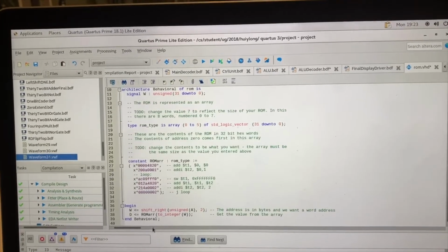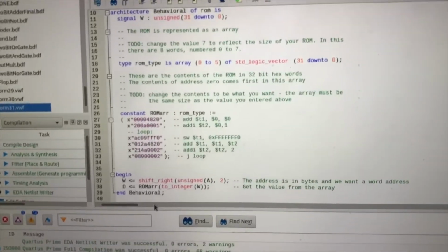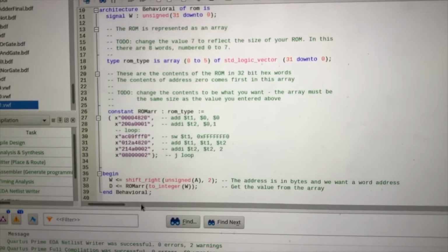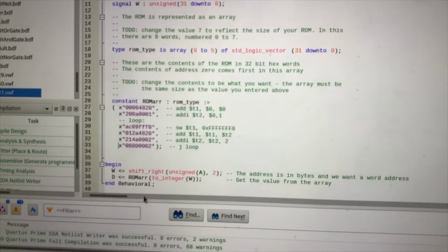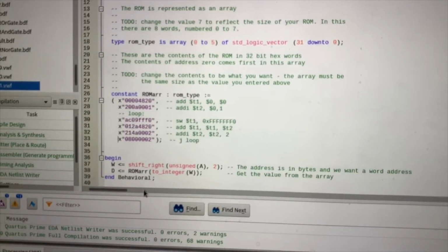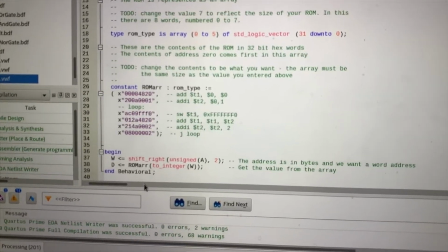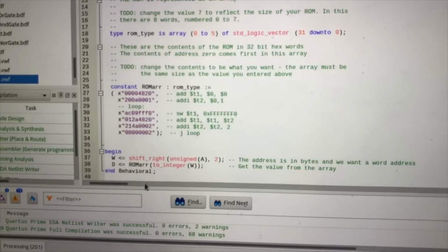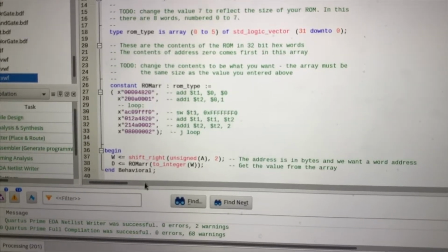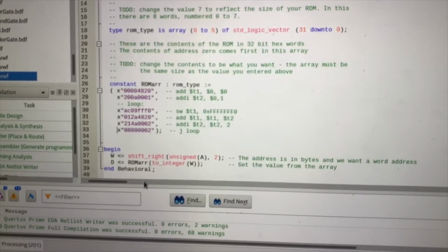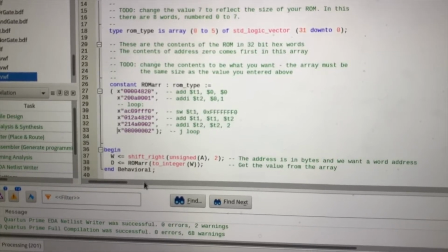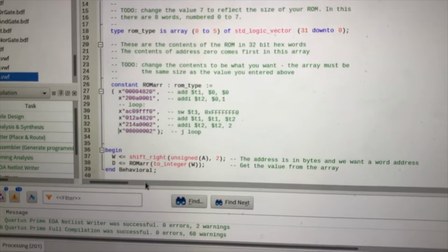This is our square numbers program that we wrote. In the first line here, we add 0 to 0 and store it as st1. In the second line, we have st2 where we used addi to add 1 to 0 and store it as st2. Now, we go into our loop. In this line, we send the value of st1 to be displayed on the FPGA, which is 0, our first value.